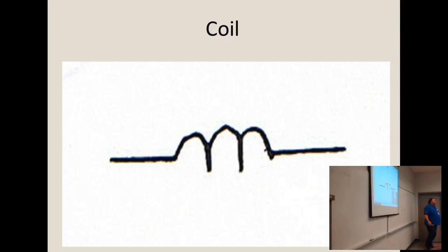And we usually give them a name that's a little more common, like CC for compressor contactor, that kind of thing. BMR for blower motor relay, or FR, fan relay. Okay, but that's what we mean. When this is labeled, then you look to see, hey, what is controlled. Now this especially can also be controlled by a sequencer. And we'll get to that later on at the very end of this. Okay?